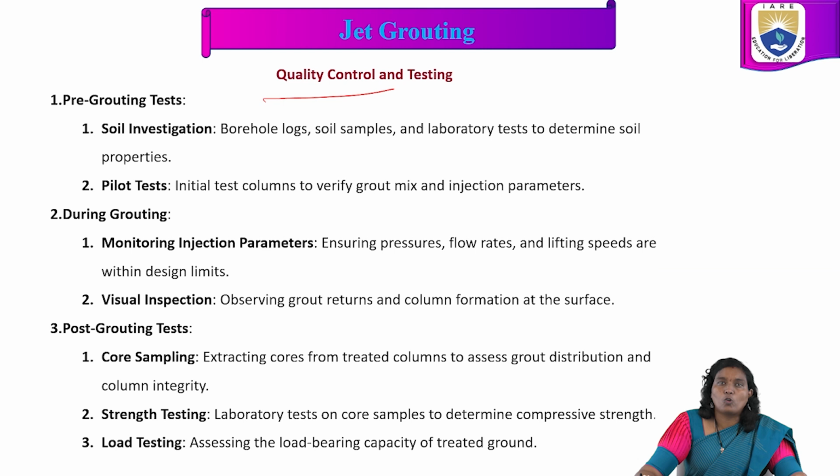Post-grouting tests: core sampling, strength testing, load testing. Core sampling: extracting cores from treated columns to assess grout distribution and column integrity. Strength testing: laboratory tests on core samples to determine the compressive strength. Load testing: assessing the load bearing capacity of the treated ground.